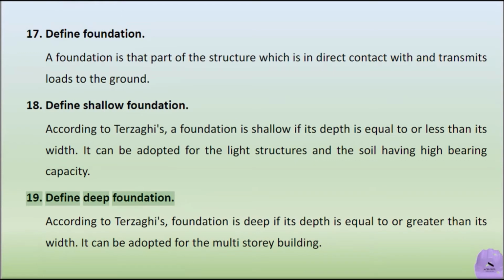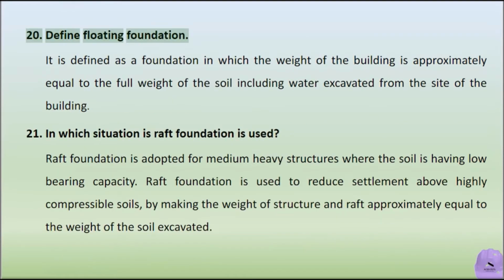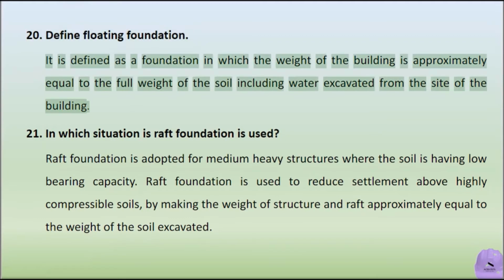Define deep foundation. According to Terzaghi, a foundation is deep if its depth is equal to or greater than its width. It can be adopted for multi-story buildings. Define floating foundation. It is defined as a foundation in which the weight of the building is approximately equal to the full weight of the soil, including water, excavated from the site of the building.